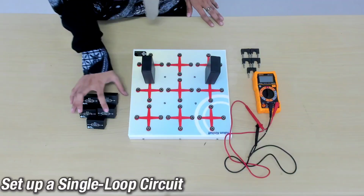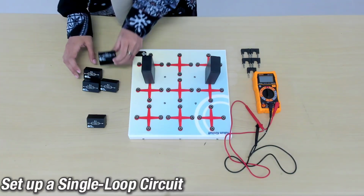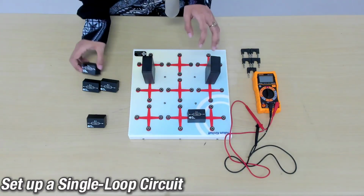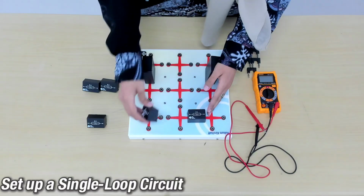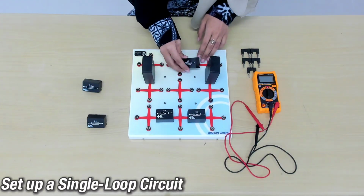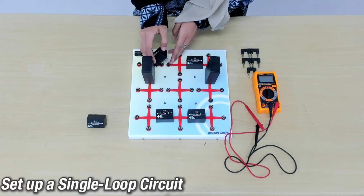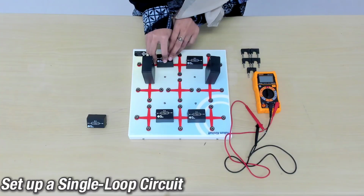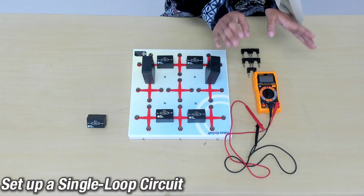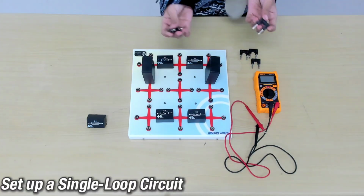Do not forget to take 4 resistors and insert them into the breadboard in series. Place R1 and R2 like this. Then also place R3 and R4 like this. Do not forget to connect them using the connectors so that they form a closed circuit.